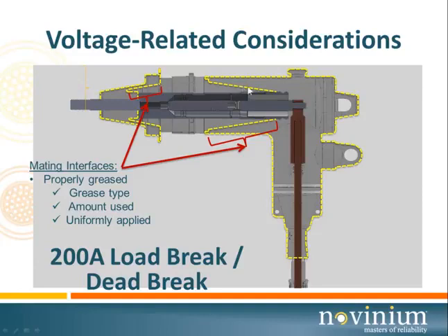It has a lower dielectric strength than the rubber, you can't have that. Just because you apply the grease to 90% of the surface, if you don't apply it to 100% all around, even on the bottom where you can't see it, you're not doing a good job of uniformly applying the grease.